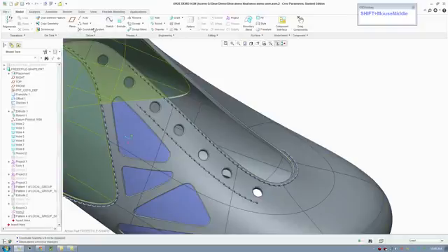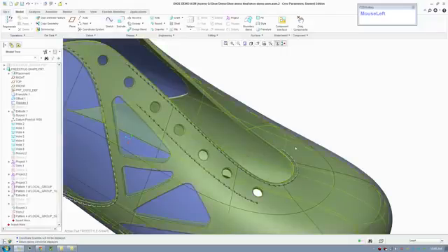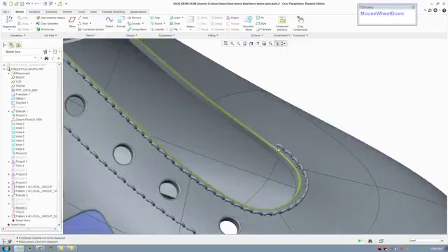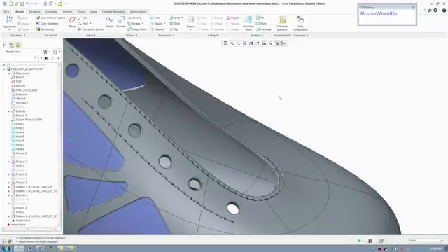So it's important to select the whole curve when you do that, and apply the tangent to curve, normal to surface axis, and use point offset to follow a line with a certain distance. So that's an advanced tutorial, and it's important to know that.